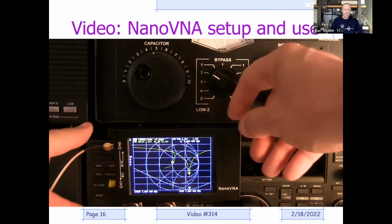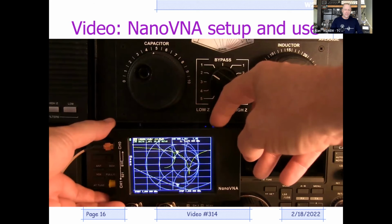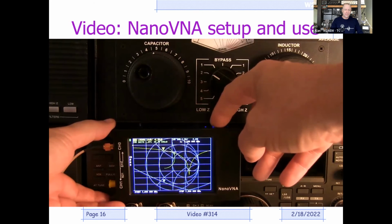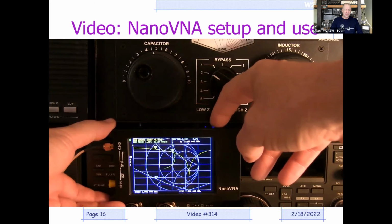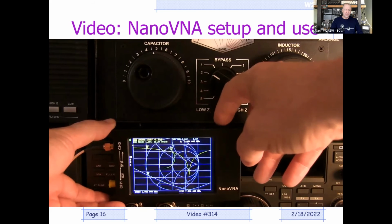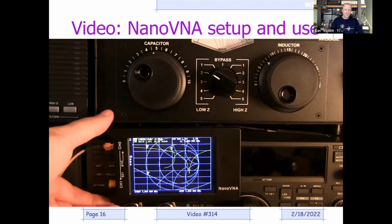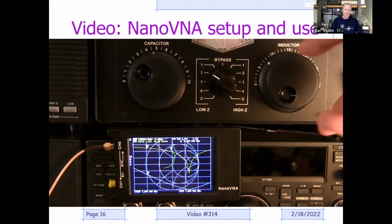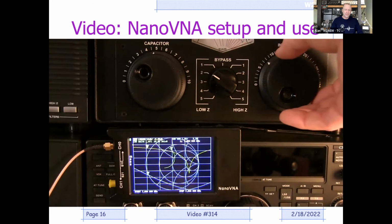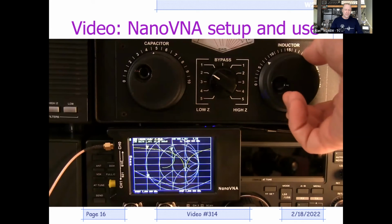Now the first thing I'm going to do is move my marker down to somewhere in the CW portion of the band, maybe around 7.07, 7.06, 7.05, something in the neighborhood. So to give me an idea, that's the point that I want to now try to optimize with the tuner. Alright, we'll start by moving some of the dials around here. Let's take a look at how the various curves move around.